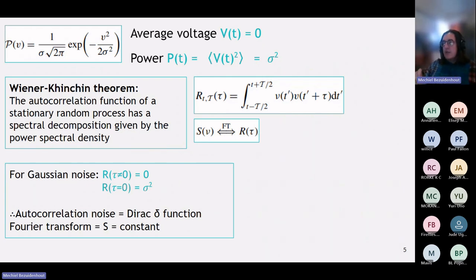And so you end up with a measurement called the autocorrelation, which is a function of that delay that you use. And so essentially what this is saying is how similar is the signal at a given moment to some other time. And the very useful thing about that autocorrelation function is that it's a Fourier pair with the flux, which we talked about last week. So if you can go from voltages, measure their autocorrelation, and then use that to give you the flux of the signal.